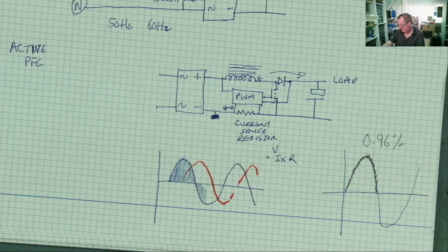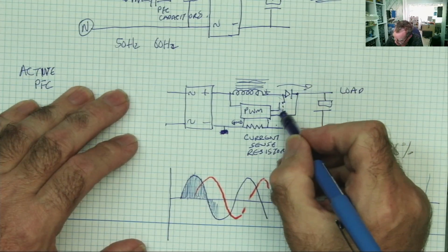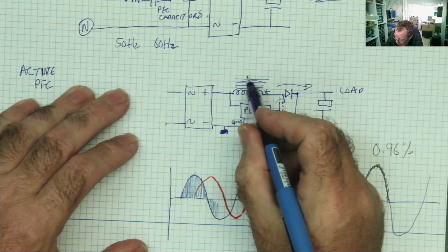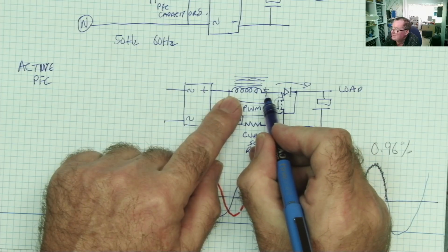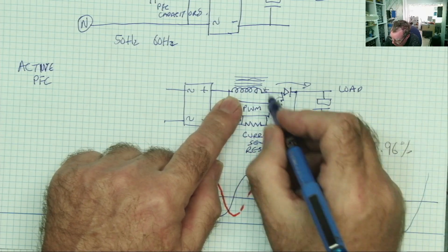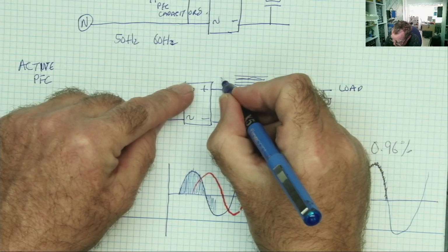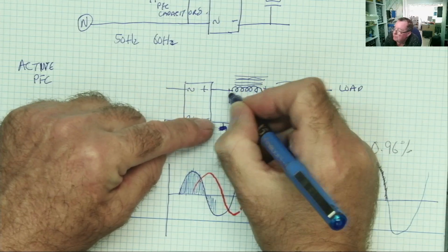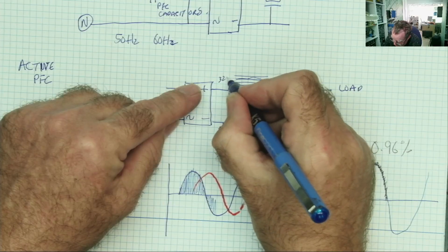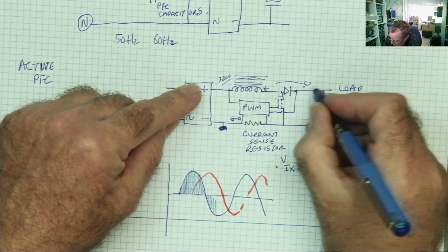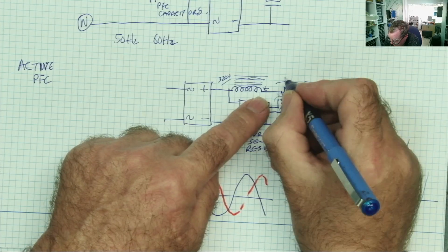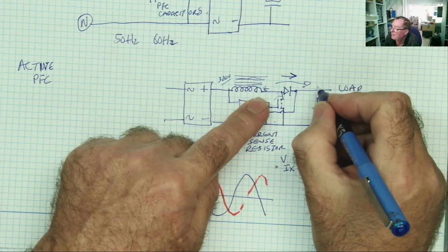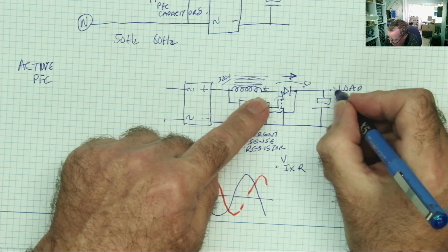One of the things. The other thing it's doing, I mentioned, when this inductor switches off, the magnetic field here collapses and creates more voltage at this end than there was originally. Okay, so the voltage here, if it was smooth, which it could do with a capacitor, would be about 320 volts. The voltage here is higher, and the diode only conducts one way, that way. Okay, conventional current, positive to negative.